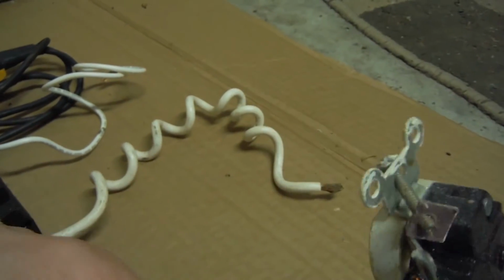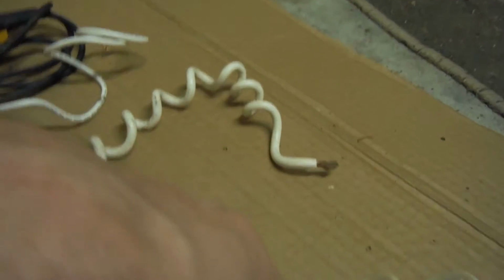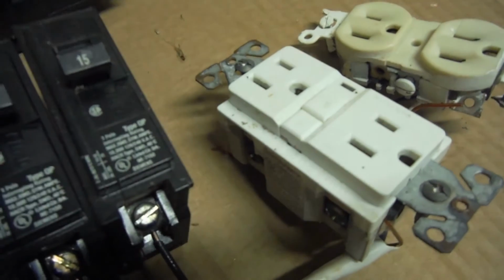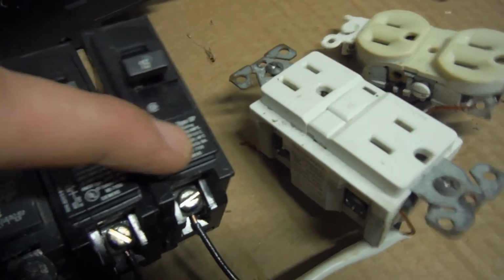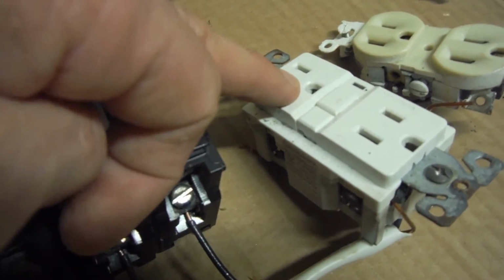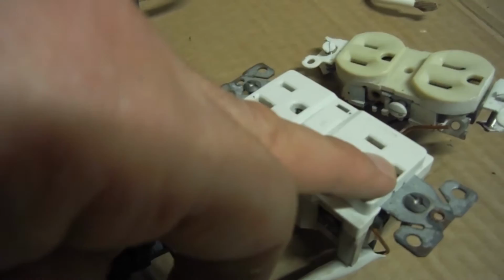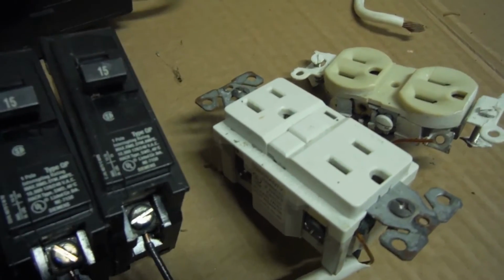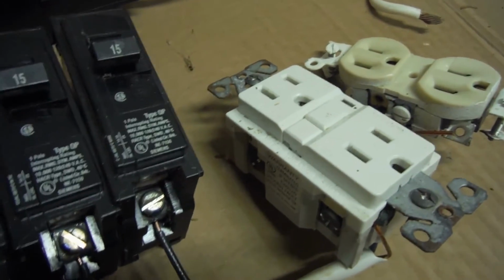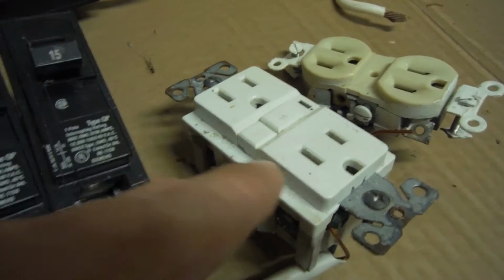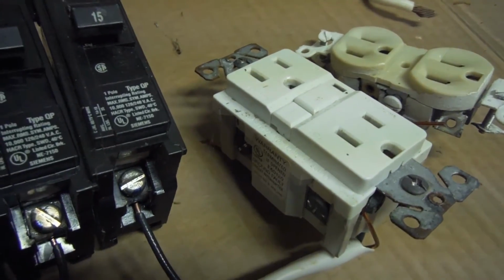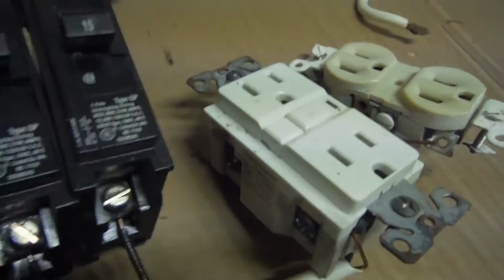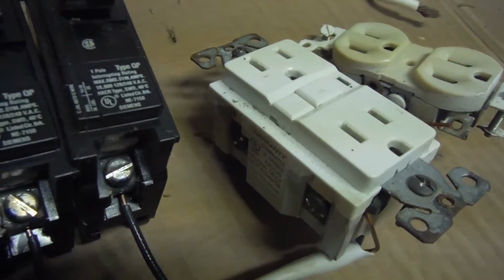So that took me a little while. Yeah, kind of slow, but that took me a little while to figure that stuff out. If you hook them up backwards, and you put your line coming in on your load, and then you put your load on your line, it's not going to work. I mean, literally, it's not even going to work. It won't even reset. You won't get power to this outlet. It won't work at all, even though you've got white into white, black into black. So, just a little advice on that.